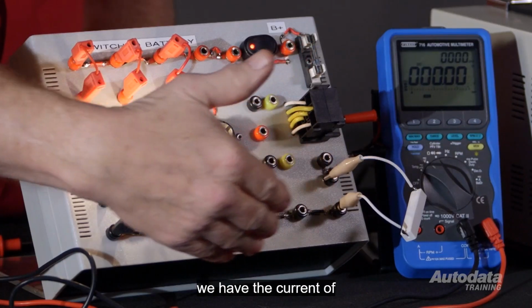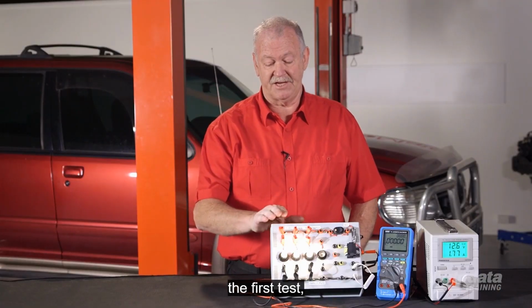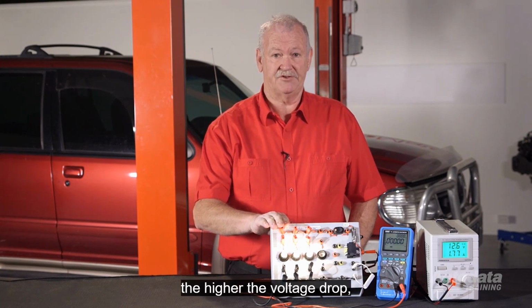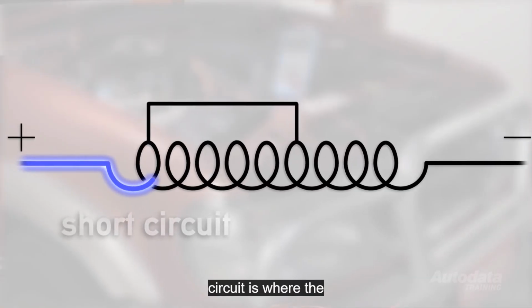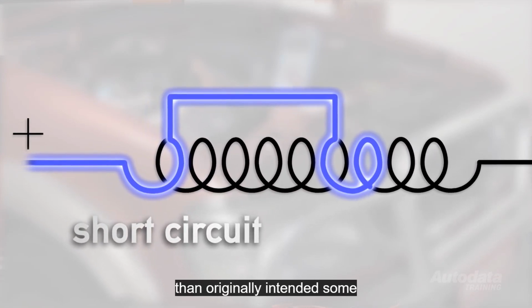This time we have the current of all three globes flowing through the resistor, whereas in the first test we just had the current of one globe. So the more current that flows through a resistor, the higher the voltage drop, even if the resistance is still the same value.